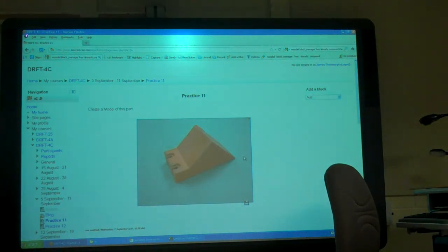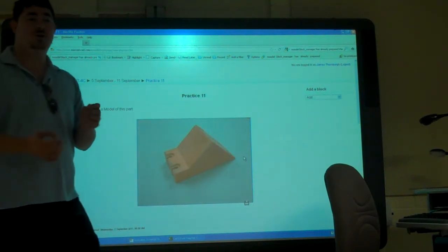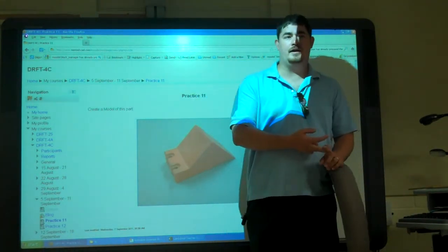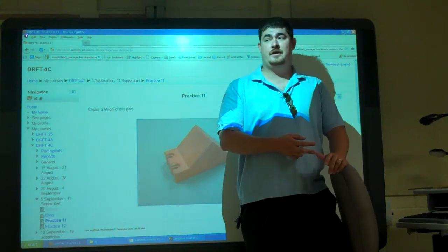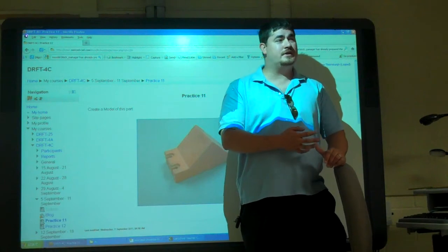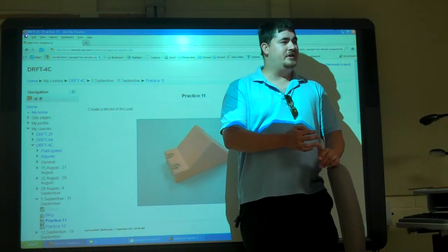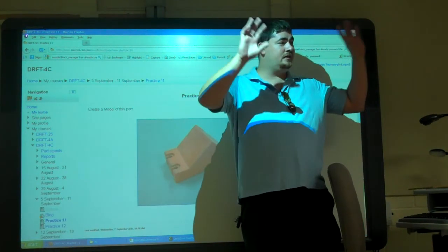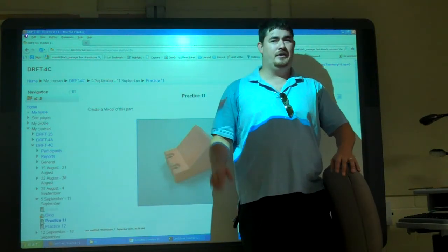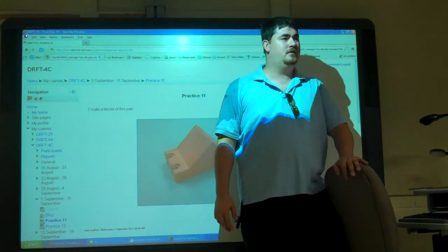So for the ribs, just draw a rectangle and extrude it down to the next thing, right? Remember to use your different terminations, so use To Next and use All. Use those terminations for things. Remember on your sketches, constrain the geometry first so it moves correctly, and then add dimensions to it. Don't start adding dimensions until it's all moving the way you want it to.